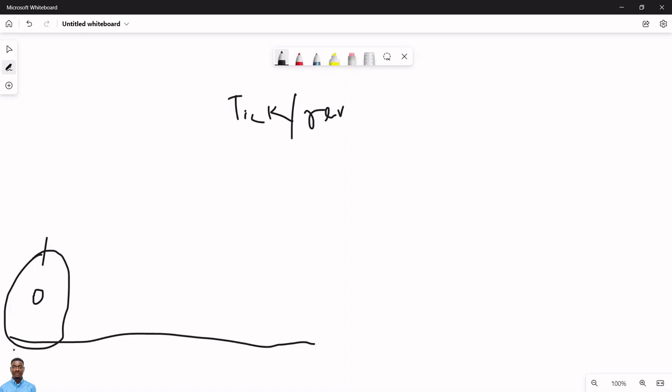So if this wheel should move this distance, maybe cover this distance, we want to know how we use the encoder ticks to know the distance covered by this very wheel. That's just what we want to explain. So the number of wheel revolutions in this case will now equal the number of encoder ticks, that is, the total encoder ticks.